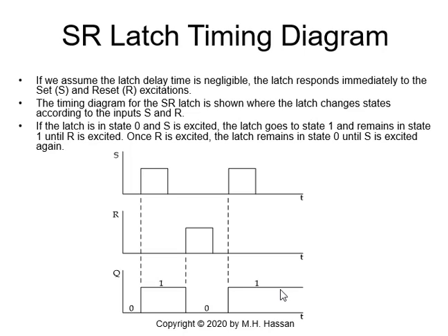There is no clock pulse; this is the unclocked SR latch, the most primitive, and we covered the SR latch in its entirety. The most important thing is the compact truth table, and how we drive it from the hardware, which is the 2 NOR gates, the 2 NAND gates and inverters, and also how we derive the characteristic equation, the excitation table, the state graph, and also the timing diagram of the latch.